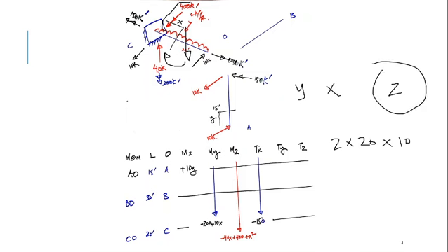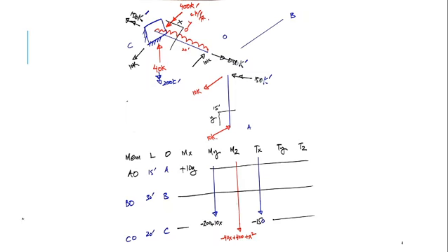So this is 400 kip foot in Z direction because this is counterclockwise in Z. You can point your thumb here and look at the curl. These are all anti-clockwise moments. This is in Y and this is in X direction. So I've been able to construct the free body diagram, and next we have to construct a moment table. If any other moment is missing, you can do it on your own.